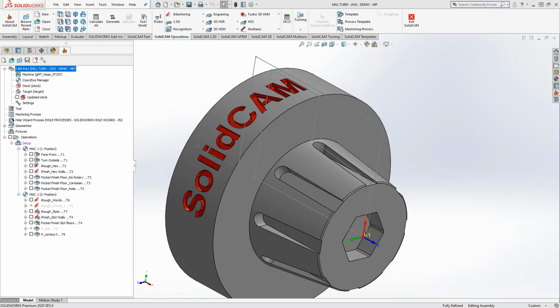You want to get all this on, not on paper, but metaphorically on paper. You want to get all this programmed. You can get all your toolpaths done, because remember, your toolpaths are based off the geometry from the target. Any stock recognition, anything like that, obviously is going to be up to date as to your stock. But if later on you change your stock definition, either using the box definition or 3D models, then you can always do a synchronize and calculate to the new stock.